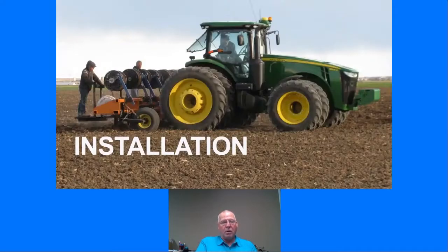Some people think that we don't have enough water to grow a crop, but what we're able to do, as Ami talked a little bit about, is we store water in that soil profile. We're putting water on during the time that the plant's not utilizing it, and we create a water pot, if you will, and we store that water in the root zone until it's needed, so that when we hit those times of ET, our requirements may be 0.33 inches per day when it's full load and trying to fill that crop out, and we may be only able to supply 0.2 inches that day, and we pull that extra from that soil profile.